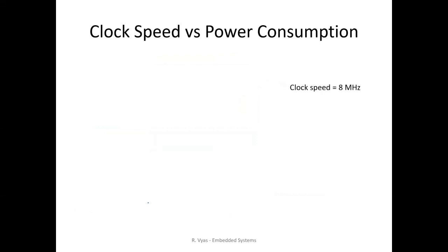And so why do you need to throttle your clock? Well, why not just set everything to run at 8 megahertz or the fastest speed, right? Well, the answer is power. The faster your clock speed, the more power your processor consumes. And so if you have things running on batteries, which most electronics nowadays do, you want to be able to throttle the speed just to conserve battery power.